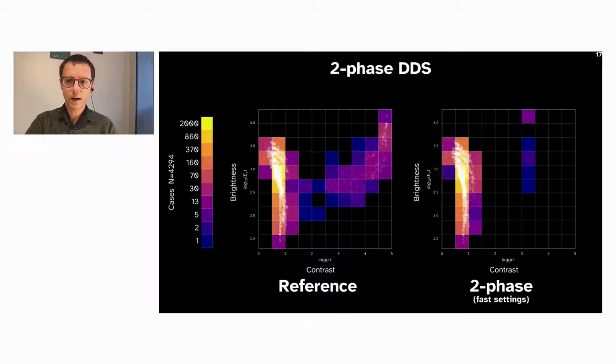To offer a point of comparison for the efficiency of ray traverse, we also tested a comparable existing climate-based daylight modeling methodology. Given our scene conditions, clear glazing with no automated controls, and our target glare metrics that require high source resolutions, we chose an image-based 2-phase dynamic daylight simulation method. Sometimes it's also known as the DaySim approach, but with a higher direct source positional resolution.